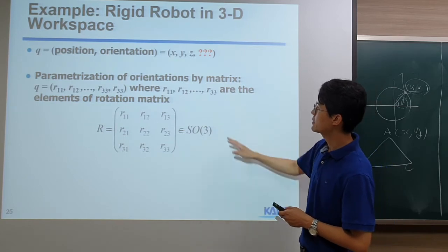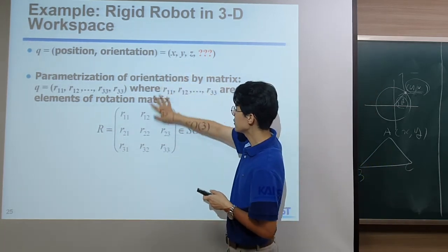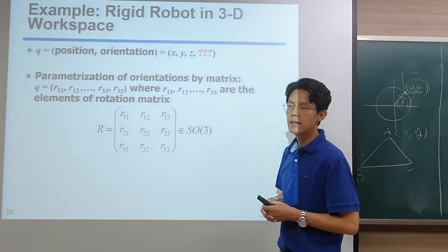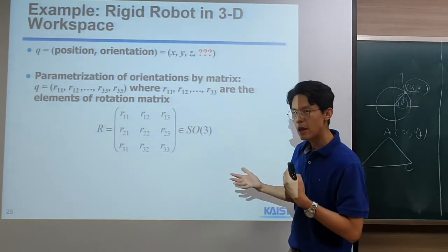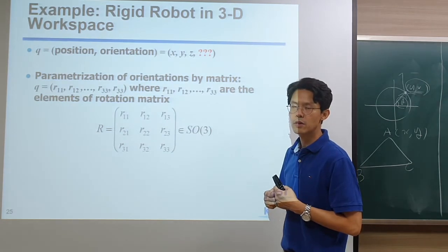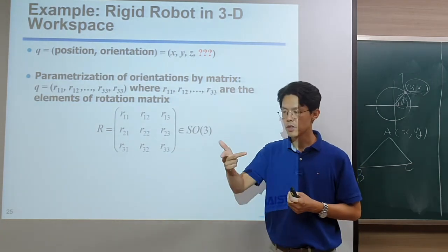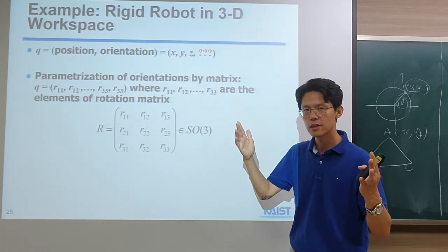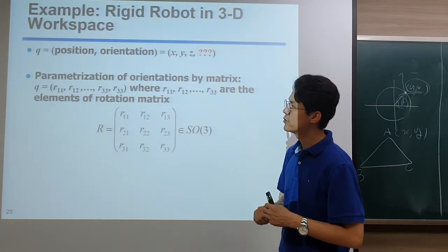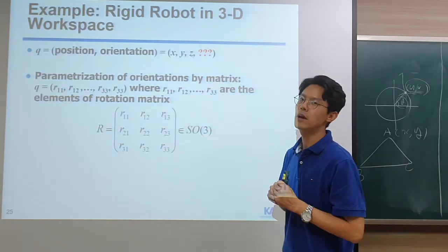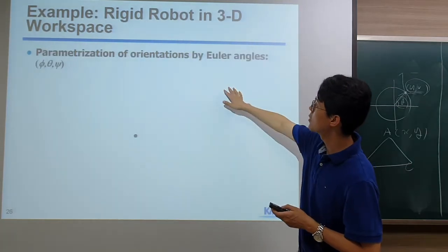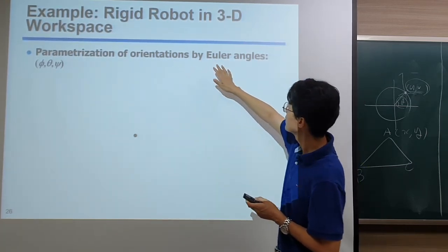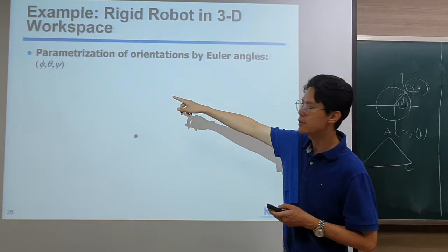And then basically for orientation, we can use the 3 by 3 matrix, right? But there could be nine different parameters. But what might be the actual freedom? You need to think about what's the actual freedom, right? We can actually change the direction, one direction. I mean, there could be many ways, but you can easily see that there are only three DOF actually. A long time ago, Euler already proved that the parameterization of orientation can be given by three values.